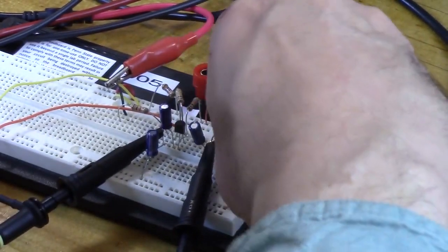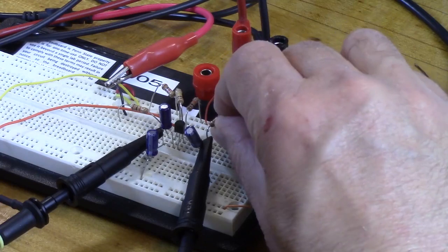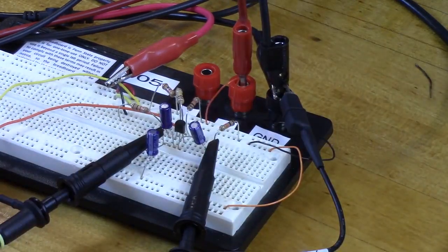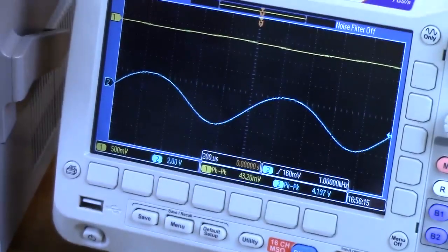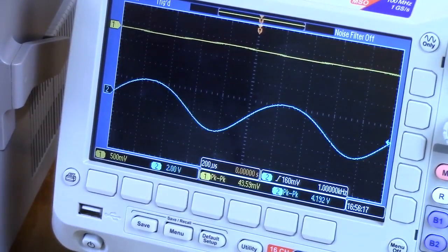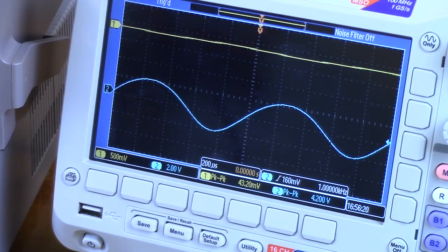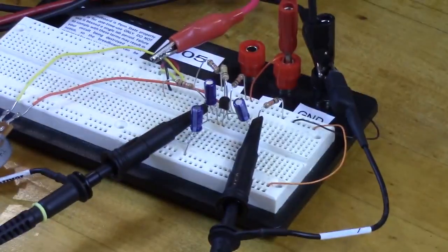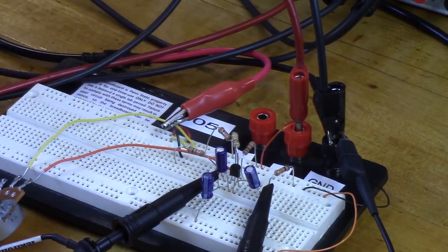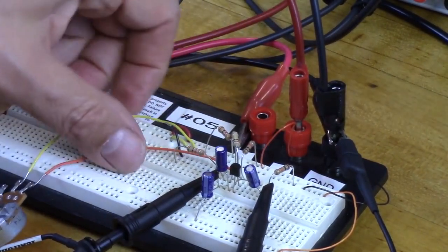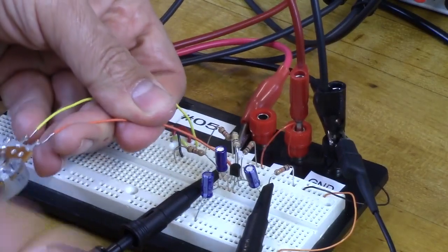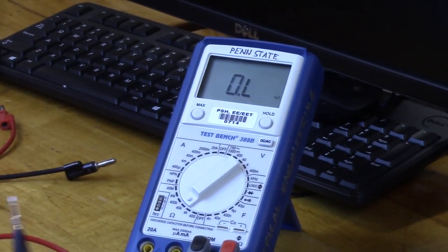So the only thing we really have left to measure, let's take out the pot for R2 and measure that. That way you can plug it into your calculations. But we can see that the amplifier gives us a lot of gain of close to 200, which is really not bad at all. So all that's left now is to take out R2 and measure it. So I'm going to shut off the power supply. We're done with that. We can disconnect this and pull out this pot for R2 and measure that and see what we had for R2. And you'll need this for your calculations.